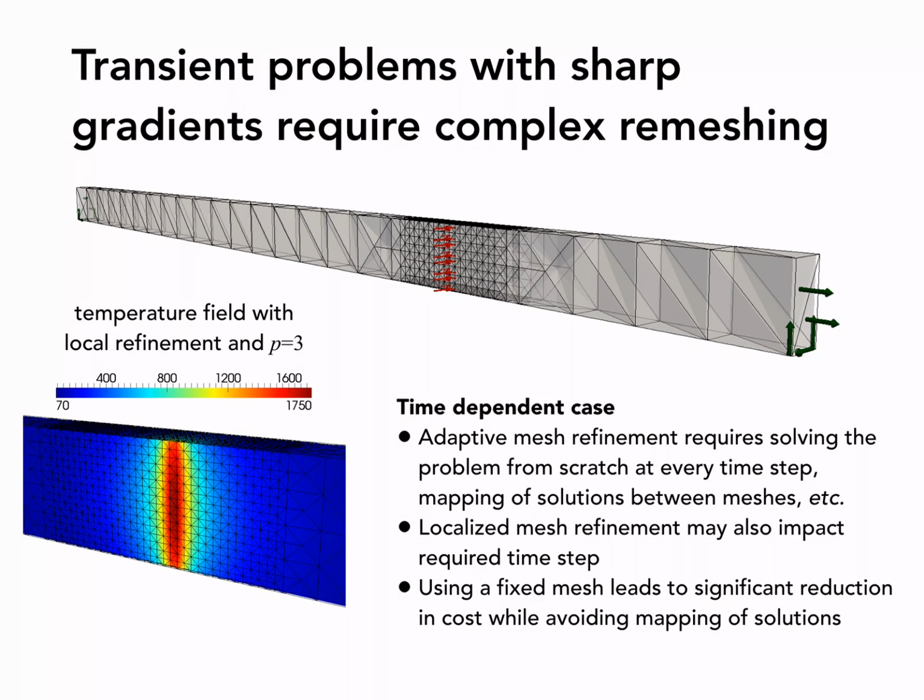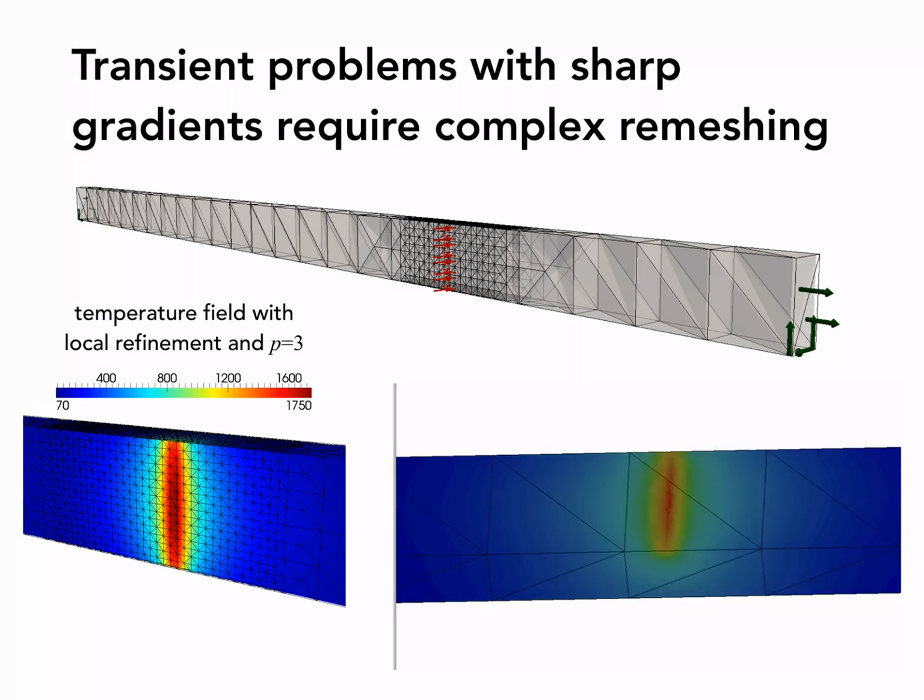Let's say you have a localized heat source. You know that you're going to have a very steep temperature gradient close to the application of that load. If you want to capture that with standard FEM, you will have to mesh it this way. Well, not anymore, right? Because if you have a function that is building that behavior into the formulation, and the function has a sharp gradient, you can just simulate that with a background mesh that is very straightforward, very simple.